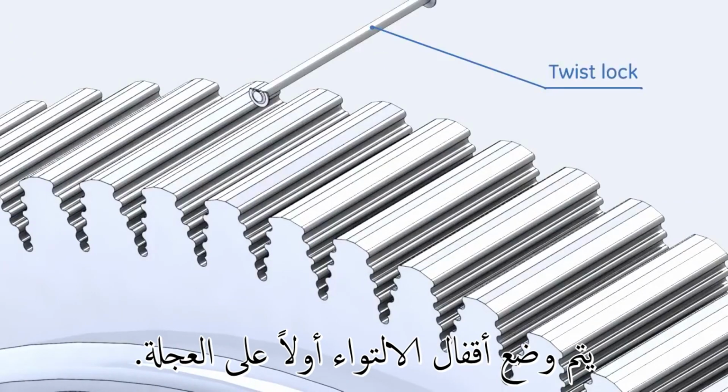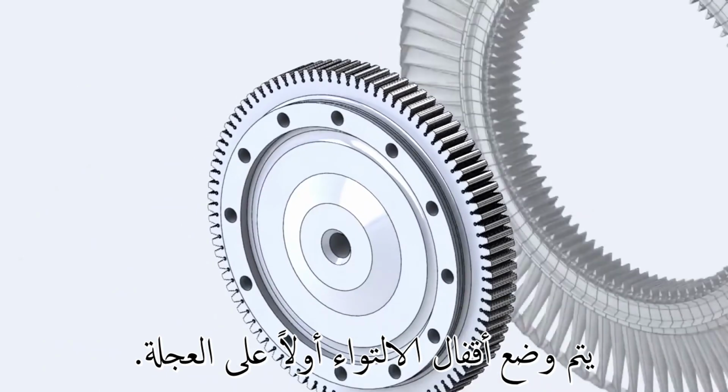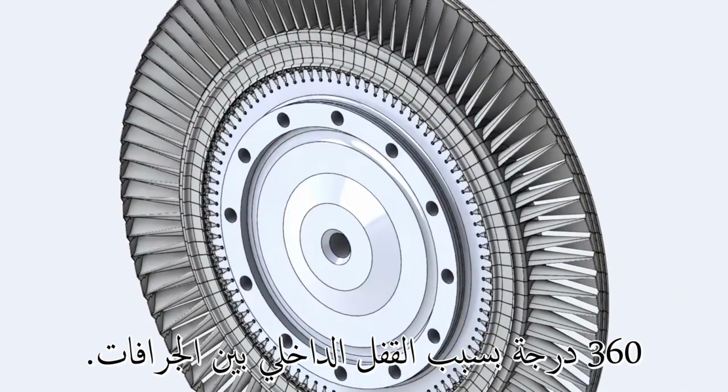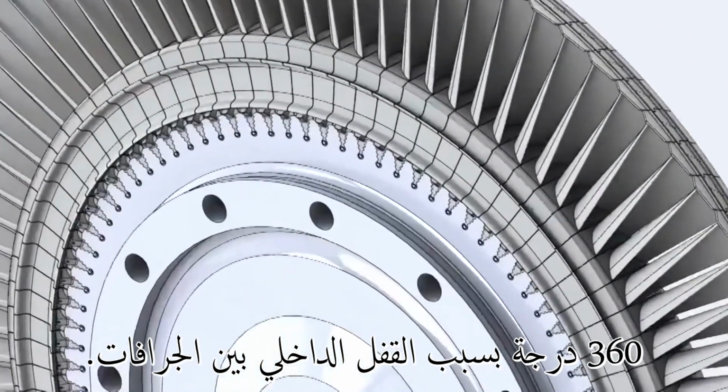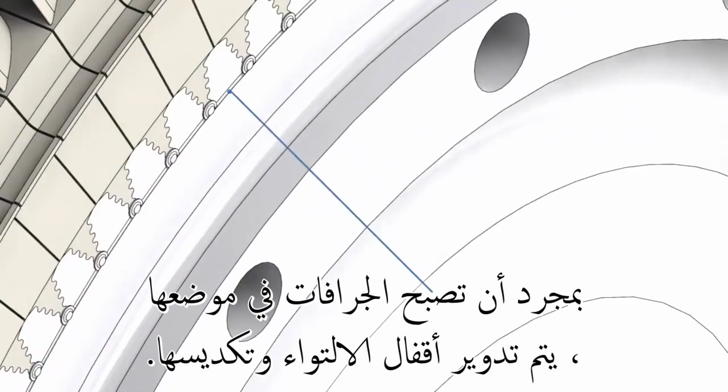Twist locks are first placed on the wheel. Then buckets are installed as a 360 degree ring due to the interlocking between the buckets. Once the buckets are in position, the twist locks are rotated and staked.